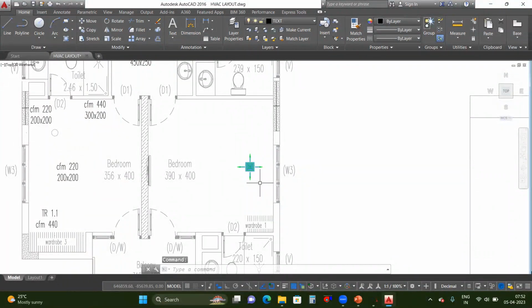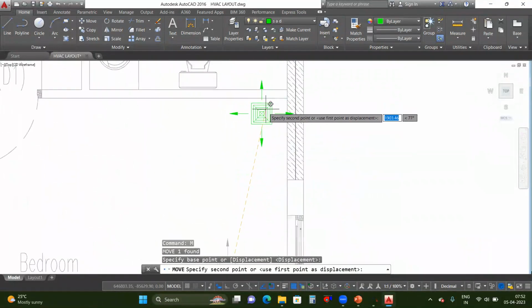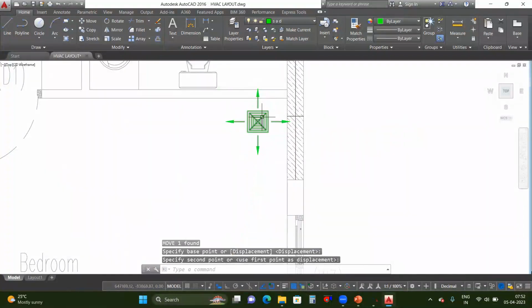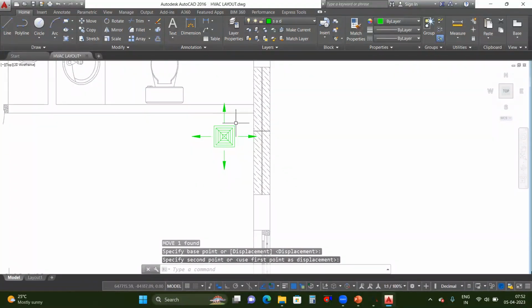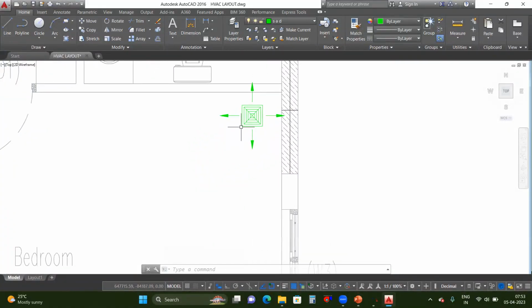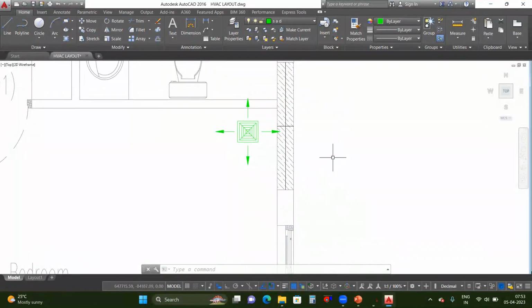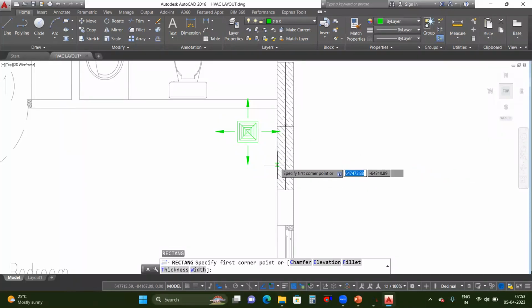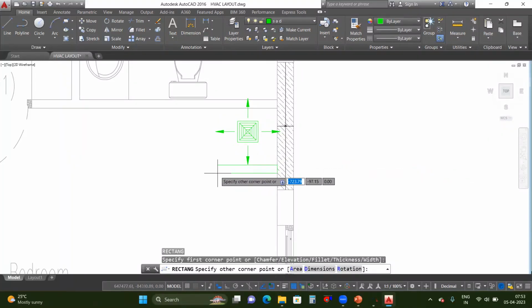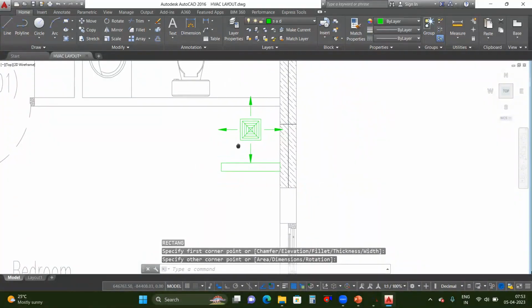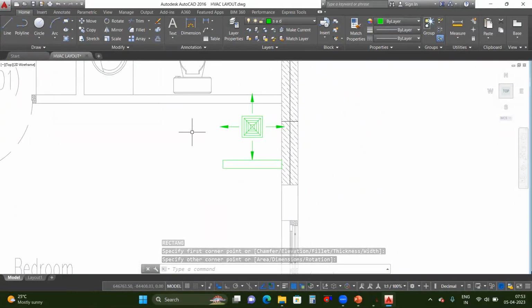three-way diffuser. So in the same situation, if we have installed it in this corner, same here also. These two sides, the air will hit the wall. So again we need to go with the two-way diffuser here. Okay. So one way and two way. These two ways will not be required here. So again, if we have one way, if we leave it like this, the airflow will be in one direction.